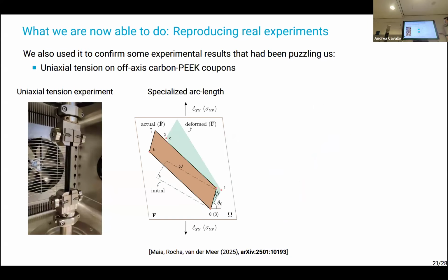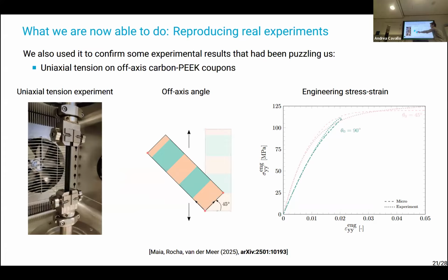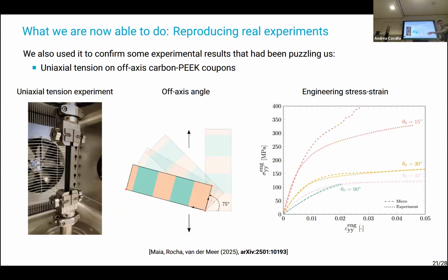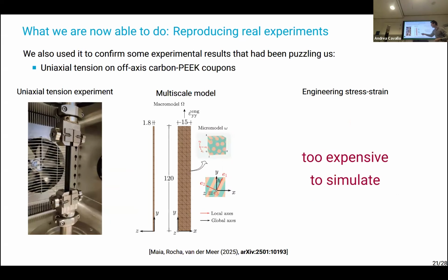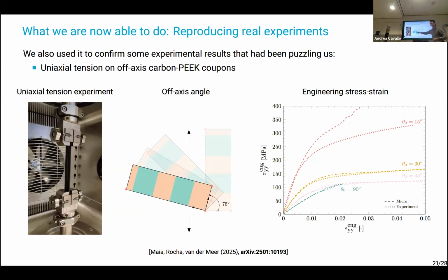And if we load it with different angles, you see that the load doesn't change, but we turn the material. We get very close to a situation where you're loading it in the direction of these fibers. So that's why if you look at the curves that are appearing here, it gets stronger and stronger, right? It gets stiffer and stiffer. And at some point, it's loaded so close to this fiber direction that the fibers start to realign during the test. It's a bit annoying to explain to you guys, but as you pull it, the fibers are almost in the direction of the loading, and then they start to move, just by deformation.